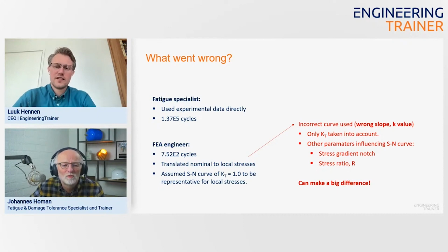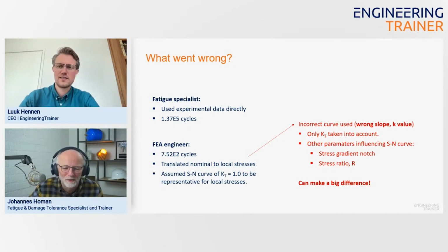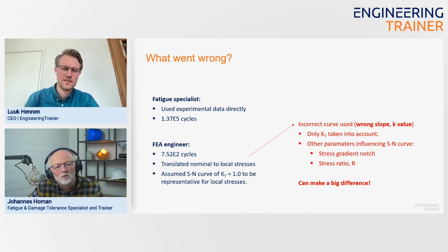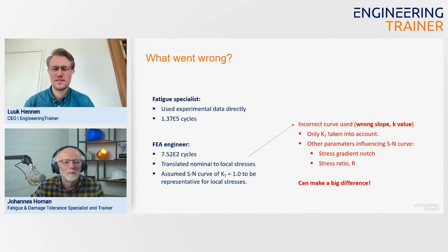So he assumes, or might assume, it's not always done that way by an FE engineer, but he might assume that an SN curve for KT1 is representative for local stresses. And that's wrong.